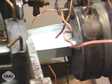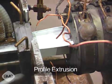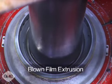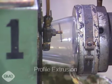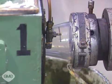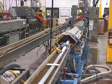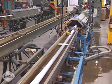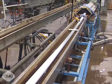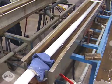Two of the principal plastic extrusion processes are profile extrusion and blown film extrusion. Profile extrusion is a horizontal process used to make long, continuous shapes having a constant cross-section or profile. The profile is extruded into a long horizontal cooling tank or trough filled with water.